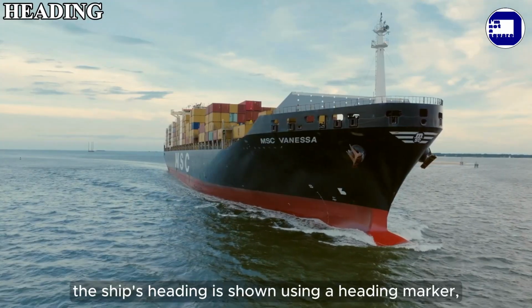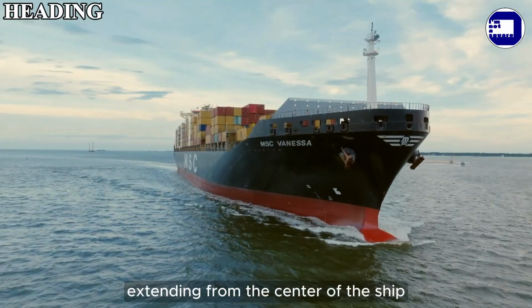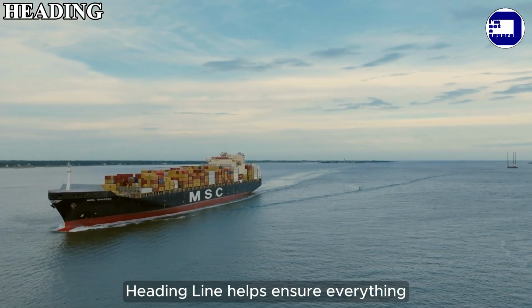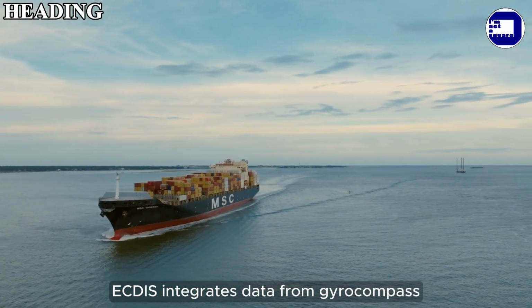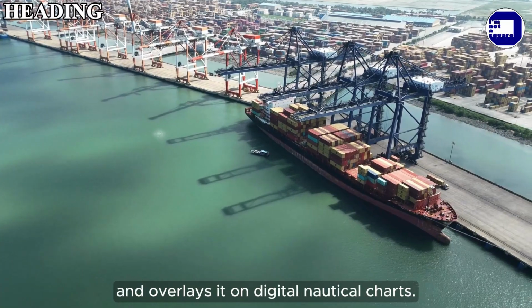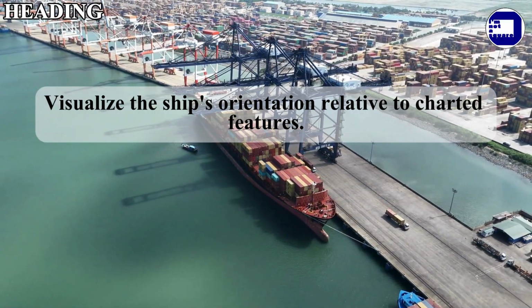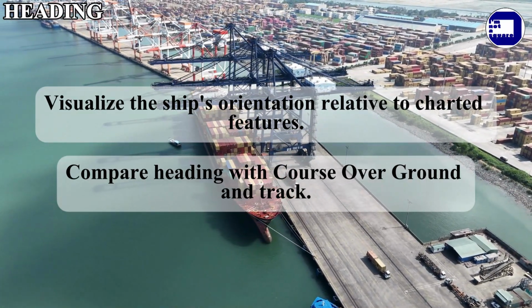On a radar screen, the ship's heading is shown using a heading marker, which is a straight line extending from the center of the ship to the edge of the screen. This line points in the direction the bow is facing. Heading line helps ensure everything is properly aligned. ECDIS integrates data from the gyro compass and overlays it on digital nautical charts. This helps seafarers visualize the ship's orientation relative to charted features, compare heading with course over ground, and track.